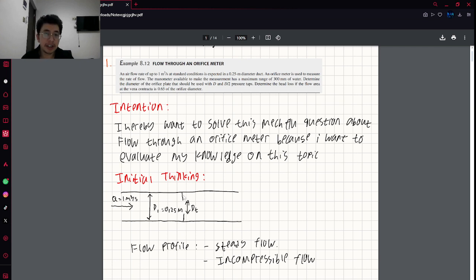So basically, it's like a 90 degree wall, and compared to a Venturi, it has a really high head loss, but the initial cost is very low. So for efficiency purposes, an orifice is not that effective. If we want efficiency, we will probably have to get a Venturi because the head loss is pretty minimal, but the initial cost is bigger.